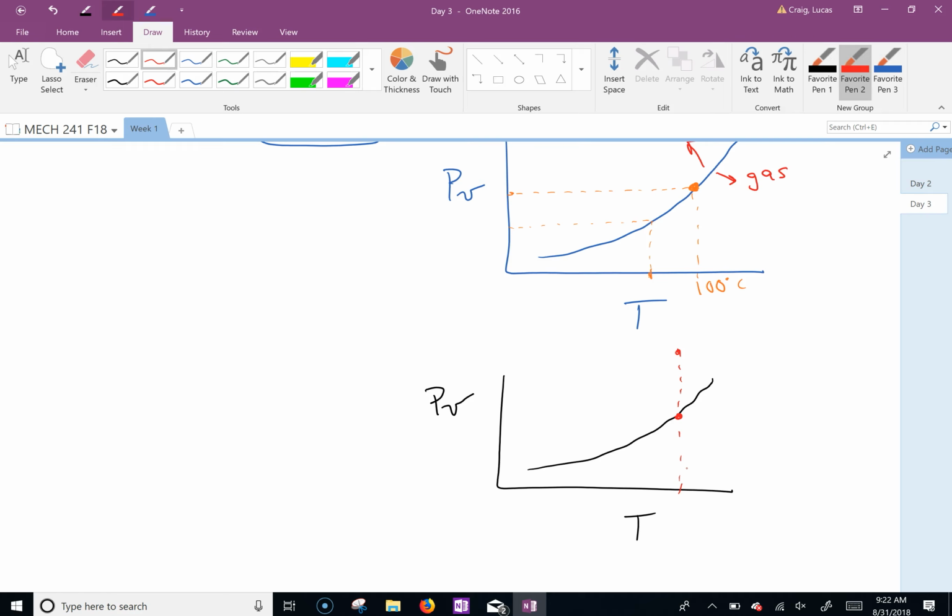So this second case, where you drop the pressure, occurs a lot when you're riding in a boat and all of a sudden you crank on the gas and the prop spins really fast. The pressure around the prop in certain spots drops rapidly. It's at the same temperature, but the pressure drops. And then what happens? We get air bubbles around the prop, and they're at a lower pressure.